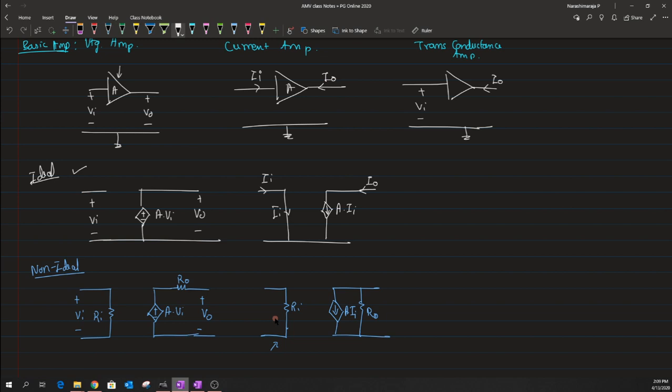The way an ideal structure would work is that if you want to read all the voltage through this amplifier, the input impedance of this component is supposed to be an open circuit, such that you can extract all the information of this Vi appearing at the input of your amplifier. So the ideal way of modeling this input of the transconductance amplifier is by having an open circuit path. And in order to generate a current component, we need a gain times Vi.